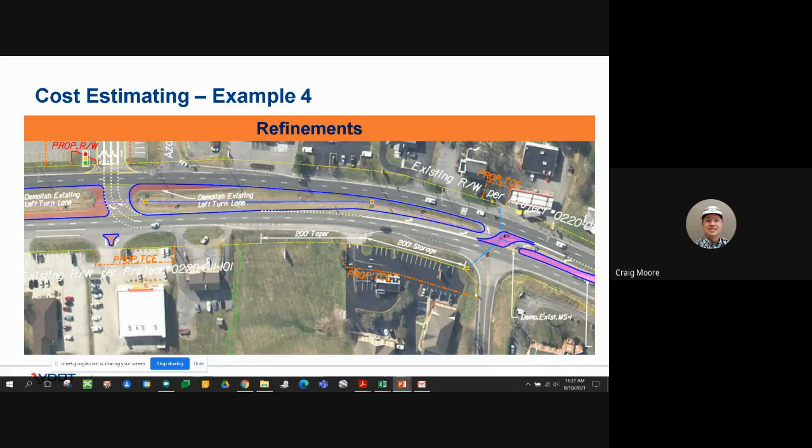Another thing on this project here, there's a water line that's running through where the signal heads are going. So making sure that we're adequately considering whether we would have to relocate that water line, or whether we will have to relocate the footer for the signal, and how that would potentially impact right-of-way. The county, the school system over here, basically we would need to acquire some right-of-way for our signal post and being able to have our cabinet there. So again, showing that information.